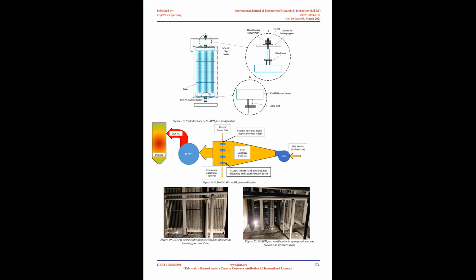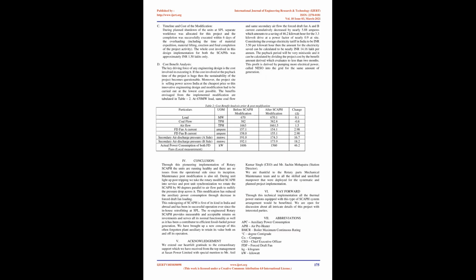Extension and modification of steam inlet line length. After extension of top duct height, the inlet steam pipeline attached to the inlet header got short in length, so to provide the passage of steam to the inlet header, we provided a spool piece, which was welded with the inlet header steam line flange, of diameter 89 mm and of length 300 mm. In that spool piece at 90 degrees, a steam pipeline with flange was provided, which was then bolted with the main steam inlet header.